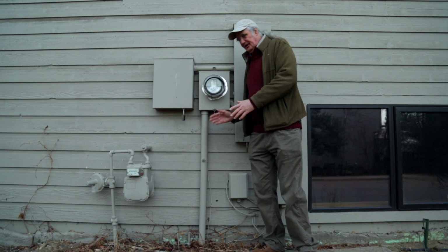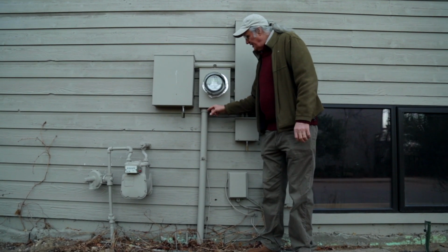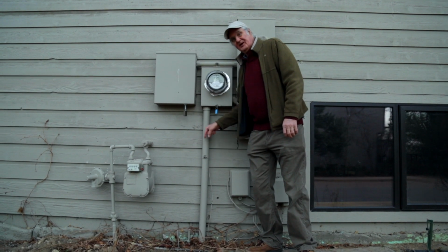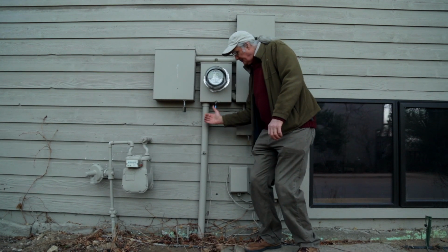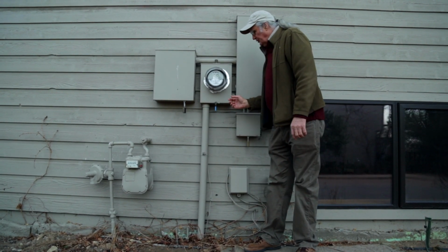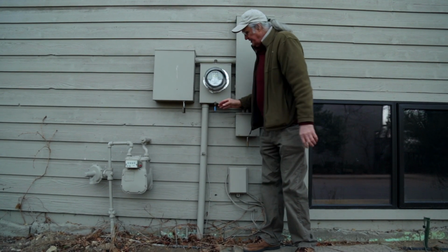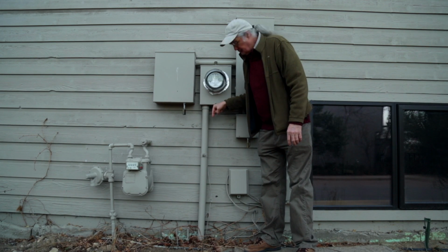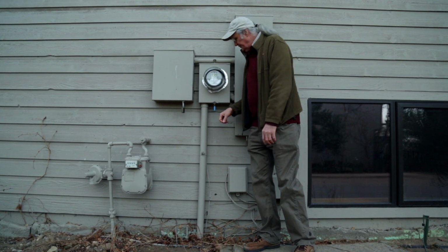What that results in is a net current. So if you have 8 amps coming in, you should have 8 amps going back out. And if that happens, the magnetic field around the incoming current going up, the right-hand rule would say it would go clockwise if you looked from underneath. That magnetic field would equal and cancel fully the magnetic field around the current on the neutral going down, which would be this way, where the electrons are going counterclockwise.